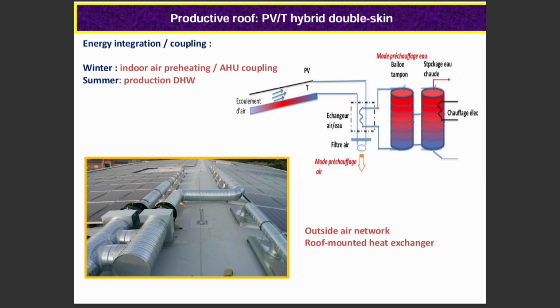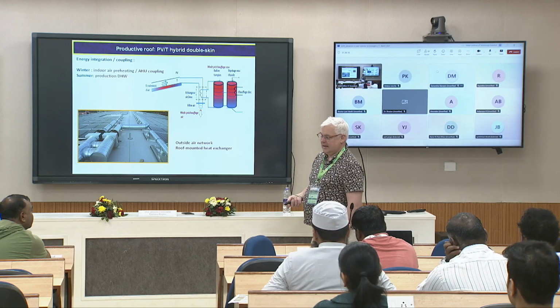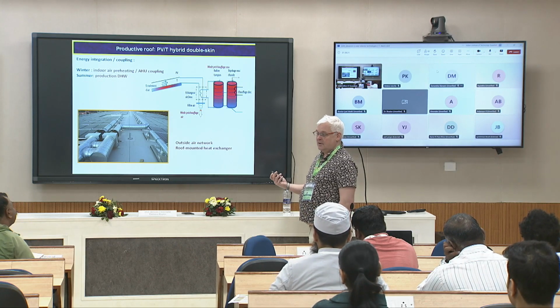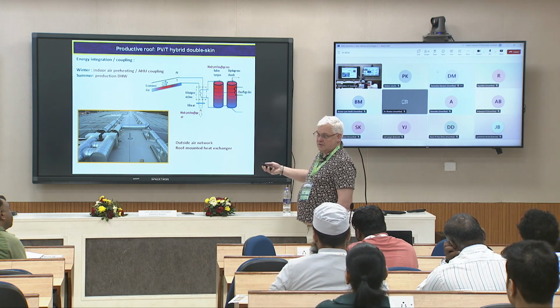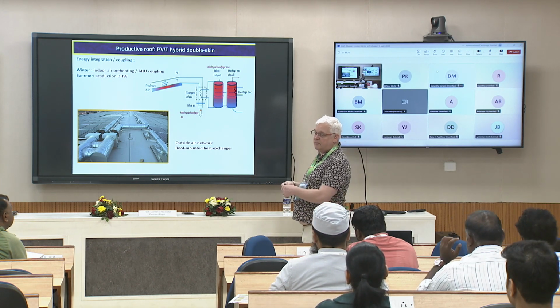But regarding the surface, the flow rate was important. It was enough to heat the water to 60 degrees. That was enough also for them to clean the tank. So heat exchange is taking place from air to water. Yes. We are losing a lot, because this is the air side, the heat transfer coefficient is very weak. Yes, that's what I was telling, it's not so good because air capacity is not good compared to water, but the quantity of hot air was important and was enough for producing the water.